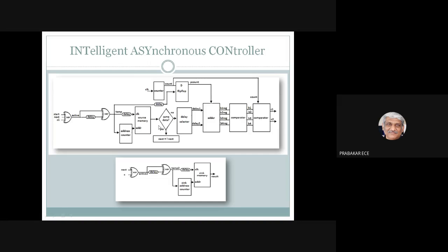So I have to wait for all the 7 blocks to work. Supposing the same data is repeating, then what will happen? I have to do the same multiplication again, right? Say for example 8 ones multiplied by all ones again, 8 ones. In that case, I will get the maximum output, and that's not a problem. But if the same data is repeating, I need not wait for the full time. Instead, since the previous data is also the same data, I can immediately latch the data for the second multiplication.